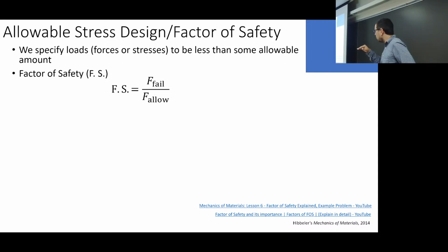But then allowable, that's when you say, hello, NASA, guess what? You really should only make sure that in operation, you get to this force. So you better design your circumstances, your environment, your mission, whatever you anticipate this part to experience with force, this is what the allowable force is. And now I've budgeted a safety factor of whatever, 1.2 or 1.3.